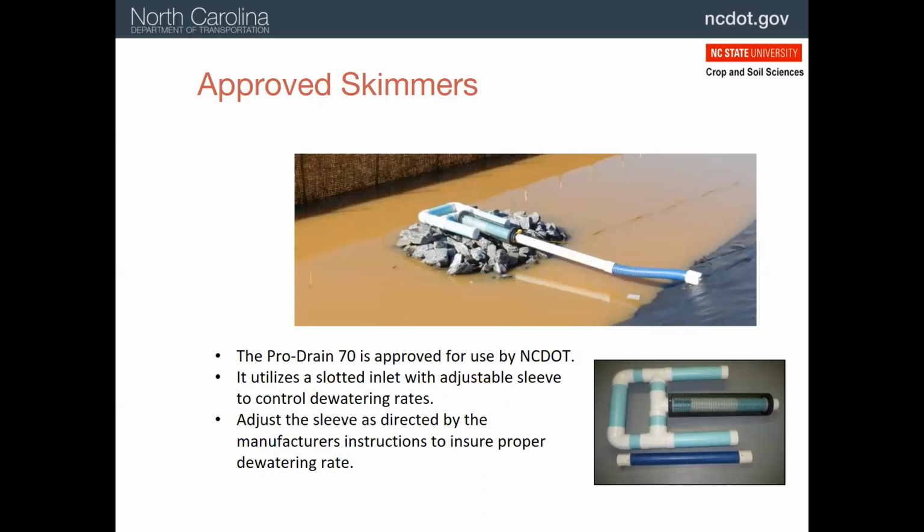Now, notice here, the outlet for the skimmer has been installed in the dam at an elevation of about 1 foot above the bottom of the basin. Now, all skimmers will stop discharging once they are level. So at this point, we're not seeing any discharge.